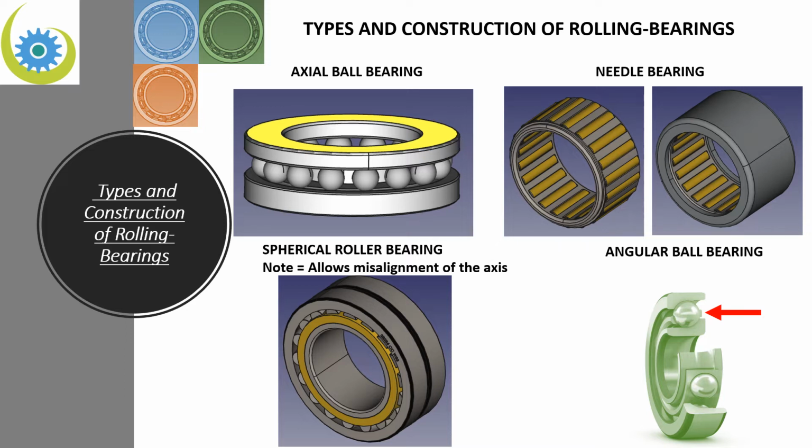Let us go on the left side below with the spherical roller bearing. This is a very special roller bearing, and it is used, for example, when we have a high deflection in our shaft, and also when we cannot assure a correct alignment of the shaft centers, taking into account the standard clearance tolerances in radial and axial direction of common bearings.